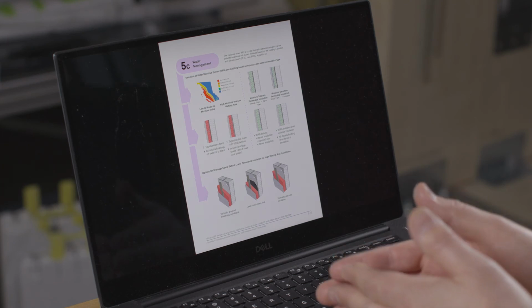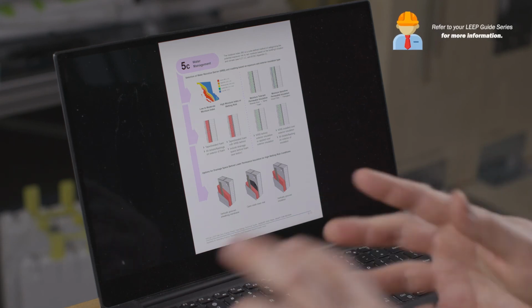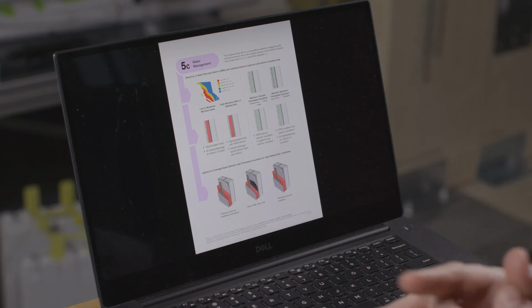with your water management. In code currently, that would be things like rain screen designs and other details for water management and flashings. Versus in low regions where the risk of water penetration is much lower, in drier parts of the country. And so there's two approaches. And this is where wall 3 and wall 2 get differentiated. So wall 2 generally recommended for low moisture index regions. Wall 3, with the details that we cover in the guide, generally recommended for the wetter regions. Okay, so you've got the two choices and you can use them.